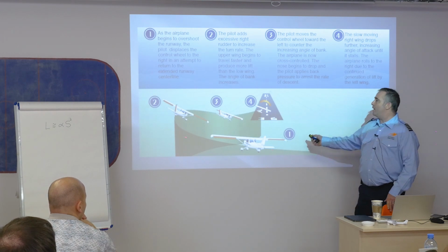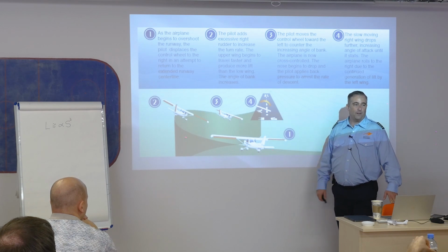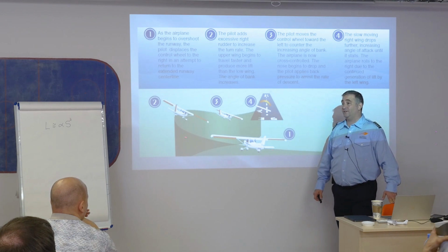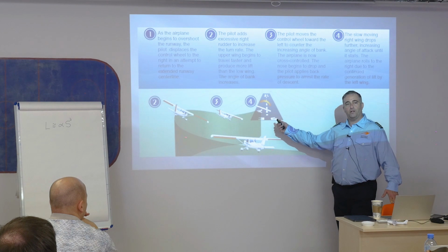Easy. So far, they've made a series of poor control inputs, or poor decisions even. How does that pilot get away from this? Well, they stalled the airplane, they exceeded the critical angle of attack. What do they need to do? Decrease the angle of attack.